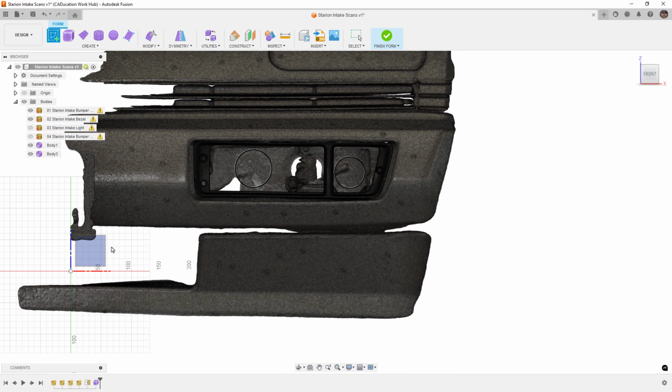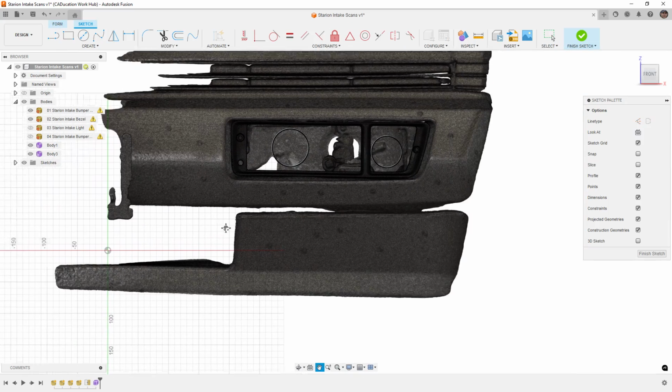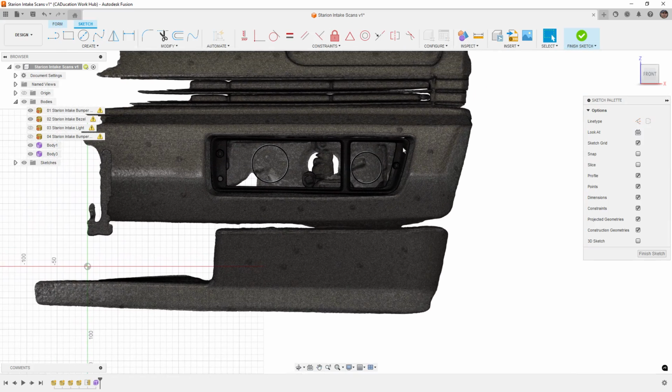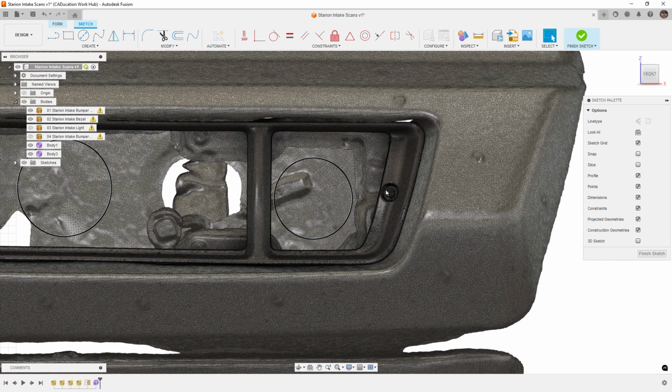So what I'm going to do is create a sketch. I'm just going to use the front plane again because I'm just going to move everything forward. And I'm going to start with this small one, which will be the brake duct essentially. And I'm going to go from somewhere down here, kind of come up over. We're going to have to go behind here because they are going to have to screw together.